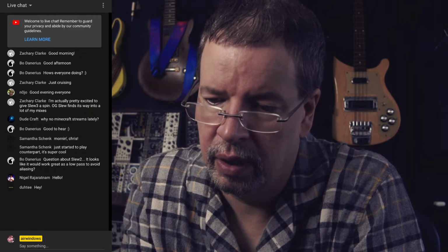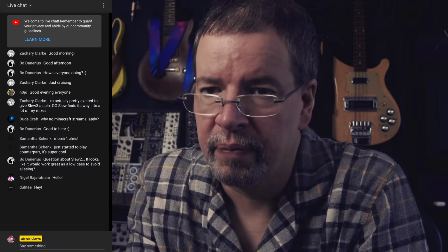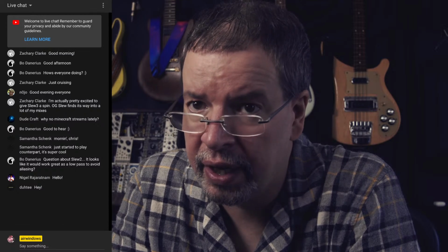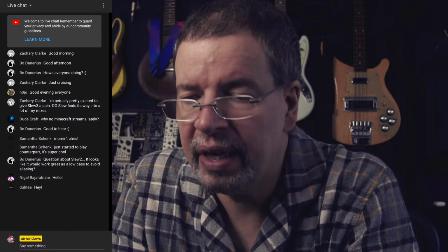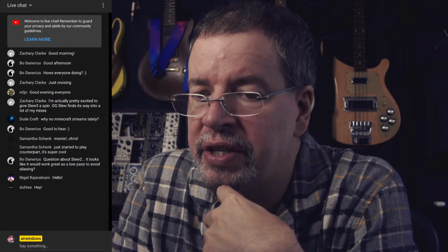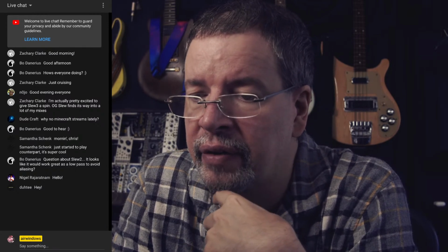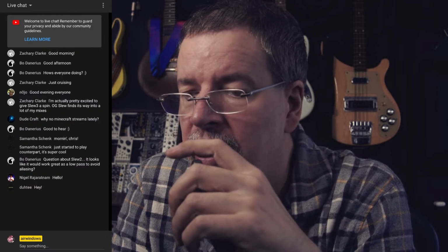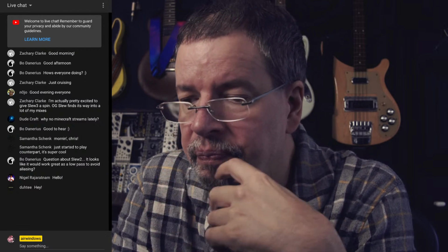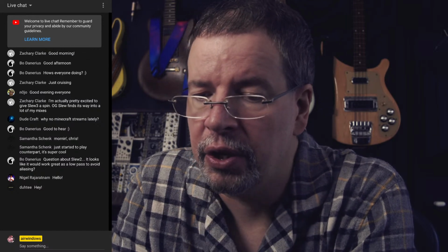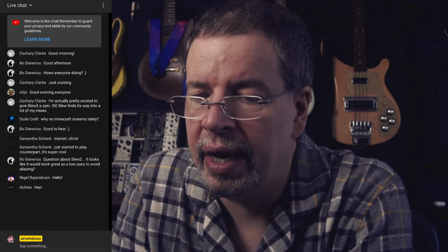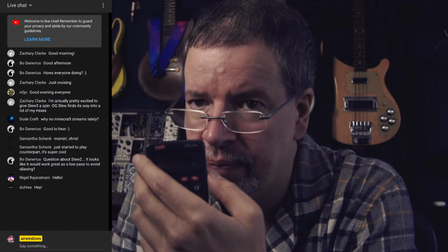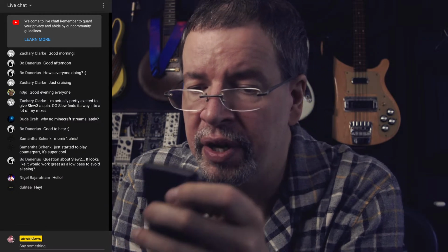So, yeah, third harmonic. If you were running at like CD quality and you were generating just the first distortion harmonic from something like Density or whatever, some very gentle distortion generator, you would need to filter at 7.35K, 7,350 hertz.